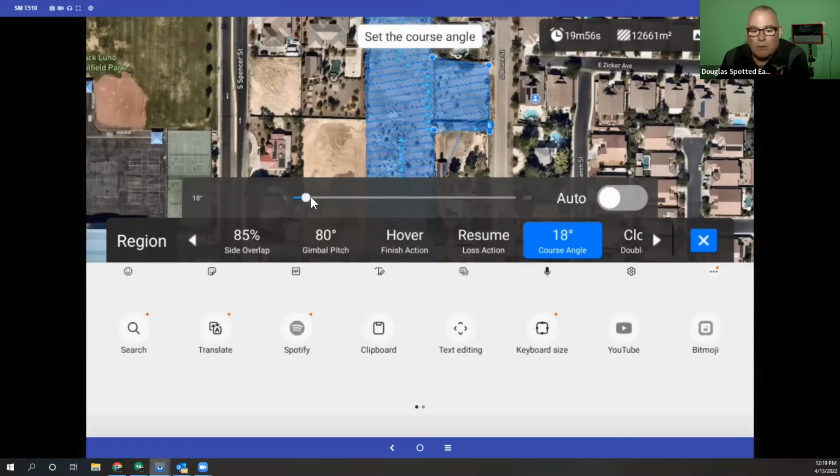We generally want our aircraft at an angle to the wind. In other words, so that one of the arms of our aircraft is pointing into the wind. What this does is it sets it up so that when we're in a crab wind scenario, we have equal pressure from the wind on both sides of the aircraft during all periods of flight. This means that our aircraft is never moving any faster in one direction or the other.